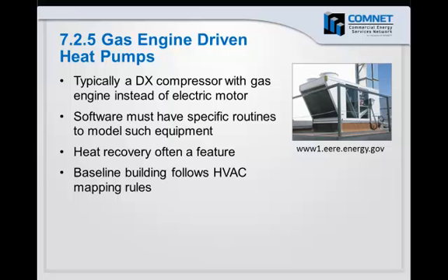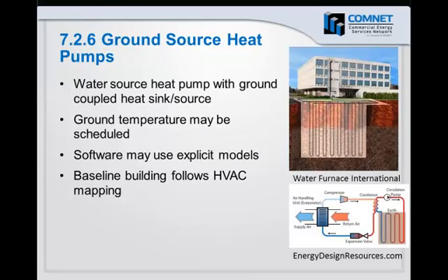Software generally must have specific routines to model this equipment because there are special performance curves for part load and so forth that apply to this equipment. The gas engine creates a lot of heat, and there's an opportunity to recover that heat. So heat recovery is often a feature of these systems that would also need to be modeled.